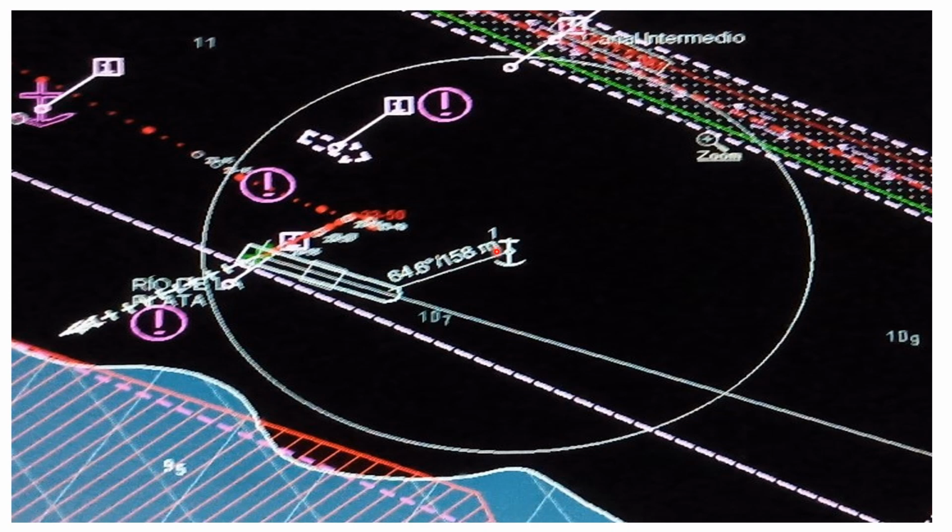The same applies before you drop your anchor. You have to make sure that inside this circle there is no other vessel, no shallow water, no nearest buoy or other danger, because this is your swinging circle. Now you see the importance of this monitoring. It's very easy to check if you are already dragging.